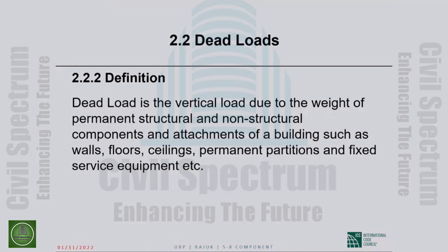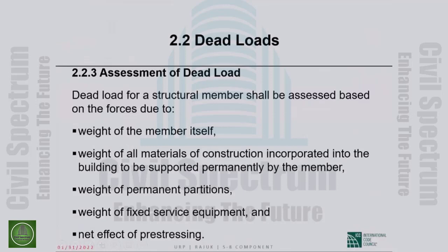Dead loads. By definition, dead load is the vertical load due to the weight of permanent structural and non-structural components and attachments of a building, such as walls, floors, ceilings, permanent partitions, and fixed service equipment, etc. You know this.